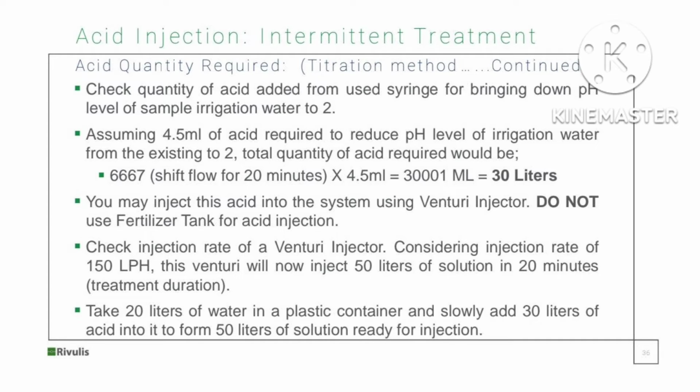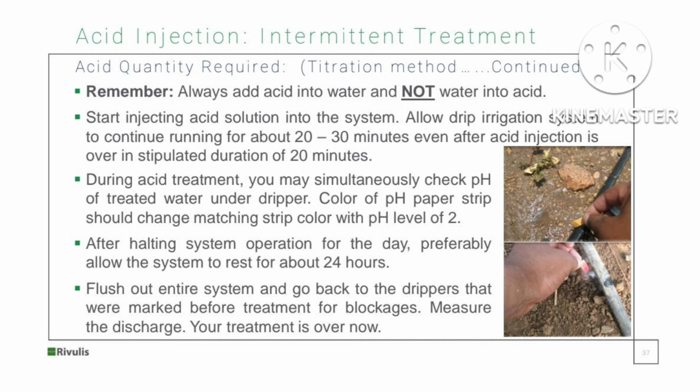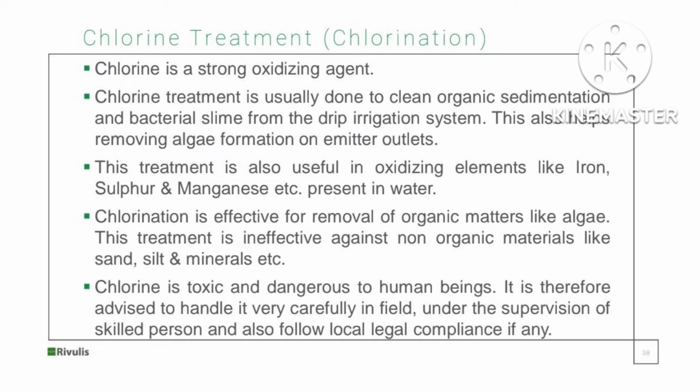You may inject this acid into the system using a Venturi injector. Do not use the fertilizer tank for acid. Always add acid into water, not water into acid. Start injecting the acid solution into the water.